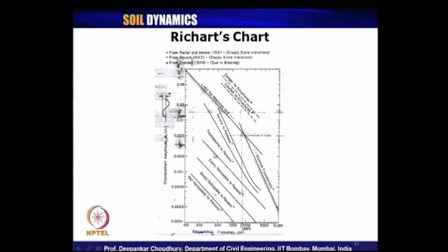So, it is always preferred to be up to the maximum of the easily noticeable to person zone, but preferably within these two zones, then you have designed your machine foundation in the best possible way. Okay. So, this is the qualitative assessment one must do for machine foundation design. But for very high values of RPM, it is very difficult to come to this zone.